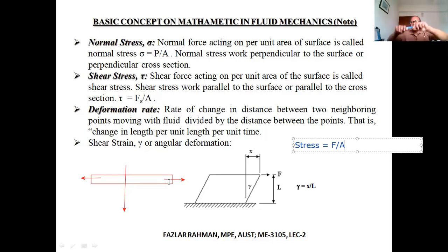And what is shear stress? Say this is the pen. If we do it like that, that means I'm applying force parallel to the cross section. That force will create shear force in the pen. If you divide the shear force by the cross-section area, you will get the shear stress. So shear stress will try to divide the pen into two parts. Shear force always works parallel to the cross section. How do we figure out the shear stress? Tau equals shear force divided by the area. And you will learn more about normal stress and shear stress in your solid mechanics class.